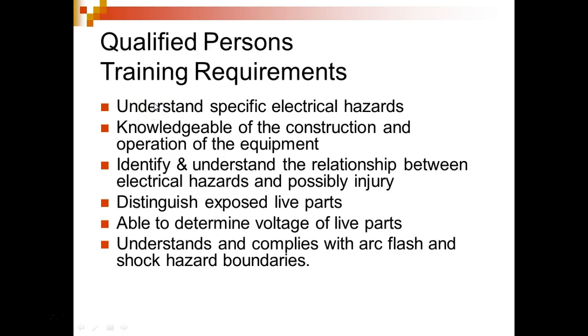Qualified persons understand specific electrical hazards, knowledge of the construction and operation of the equipment, identify and understand the relationship between electrical hazards and possible injury, distinguish exposed live parts, be able to determine voltage of live parts, understand and comply with arc flash and shock hazard boundaries.